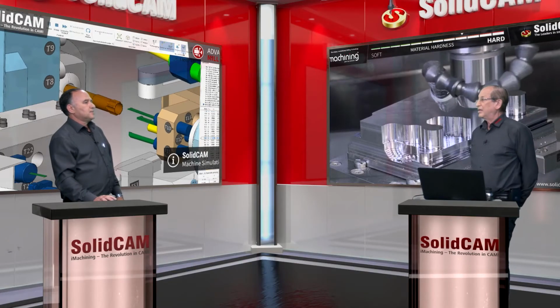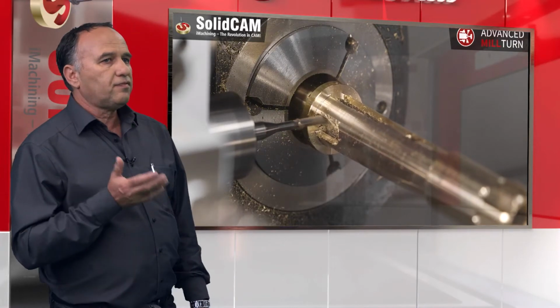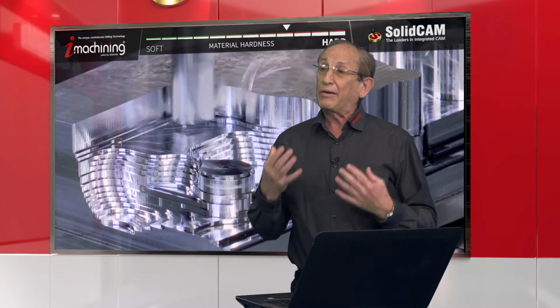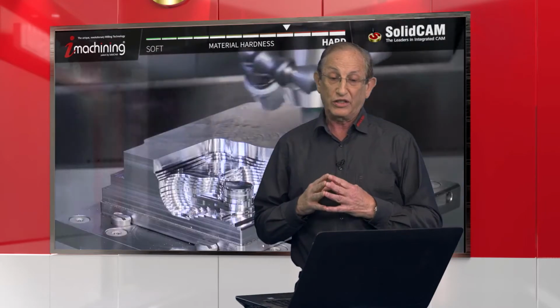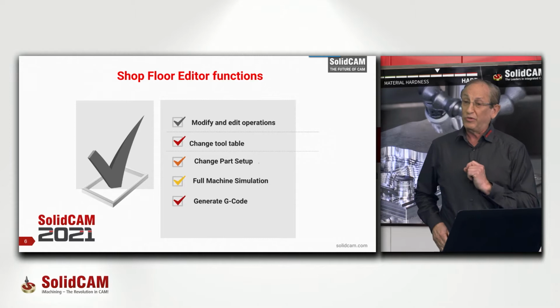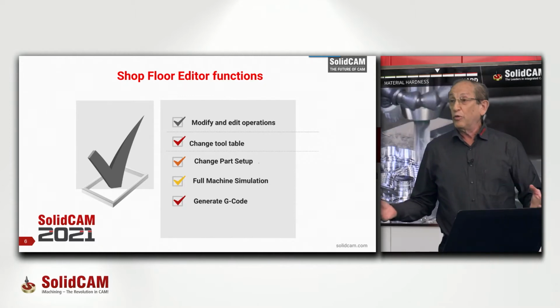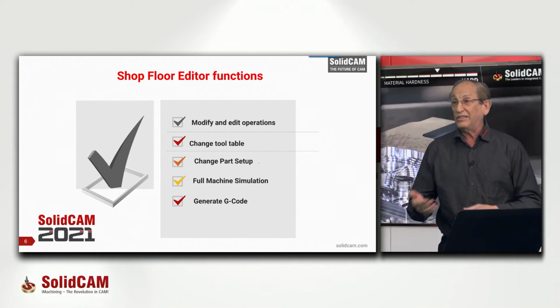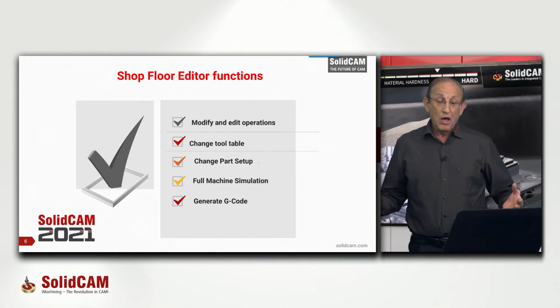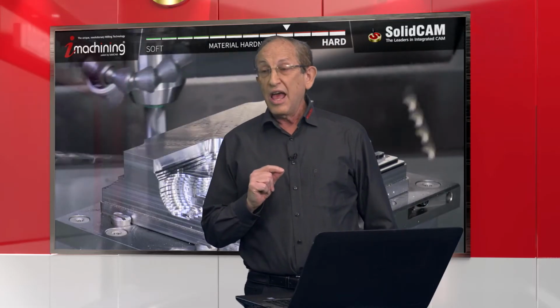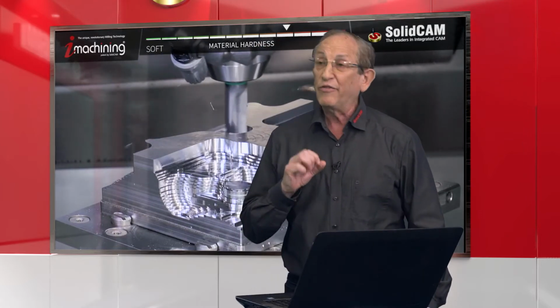Sidney, please tell us what the setup operator benefits from the shop floor editor. Well, Zvika, first, you have the capabilities of modifying and editing the operations. Yes. Also, he can make changes in the tool table. He can also make changes in the setup part. For example, if he has a different machine now he has to work on, he can change that in the setup part. He has the full machine simulation. And by full machine simulation, I mean everything, including the new SolidCAM simulator and also machine simulation. And of course, since he did make changes, he also has to be able to generate a new G-code.